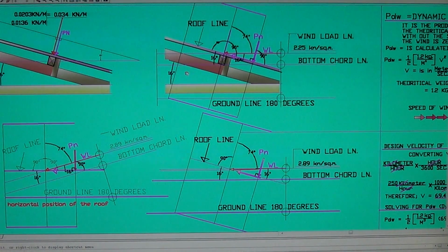See, this is 16 degrees with respect to the ground line, right? So if you position the roof parallel to the ground in a horizontal position, carrying the wind load, this is what happens. Look, the wind load is right here. Now the roof, I rotated it at 16 degrees parallel to the ground. This is like the ground now. Carrying the load, what happened to the load? When the surface is inclined, any load is an inclined load. So this is what happened.